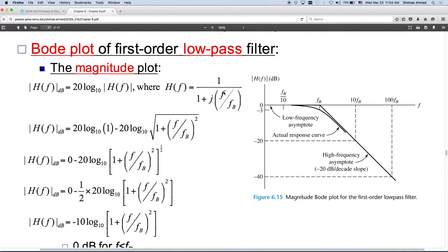So we talked about the transfer function for the high pass filter before. So this is the low pass filter. We derived this before, right? And this FB was 1 over 2 pi RC, right? So this is something known. This depends on the circuit that you have in the system, and the only variable that we have here is F. We came up with the magnitude, we drew the magnitude and phase angle of that before. What we're going to do now is take the magnitude and phase that we came up with before, and just apply this equation to it.